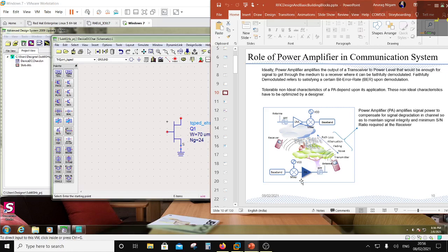Now what happens is, whenever you do frequency conversions, right, then the spectrums fold over each other, and this may result in more noise than what you are expecting, right? So in that case, you might have to filter out the signal in a certain frequency band, so you are going to receive in a certain frequency band. This reduces the noise and improves the signal to noise ratio. That's why you are going to see a band pass filter both on the transmit and receive side, right? So this basically comprises what is known as the radio front end.